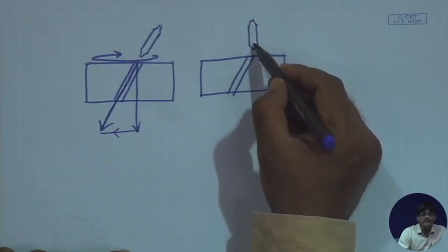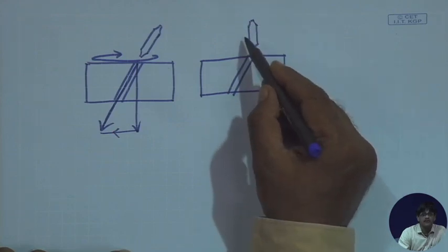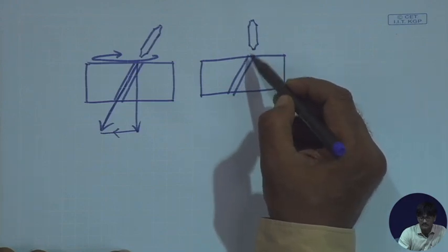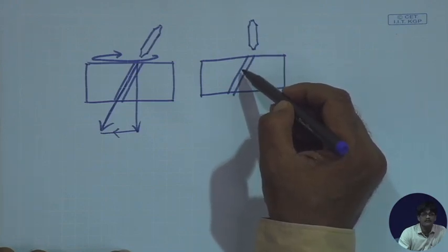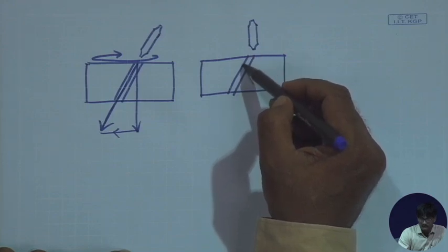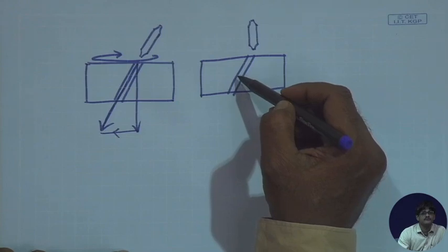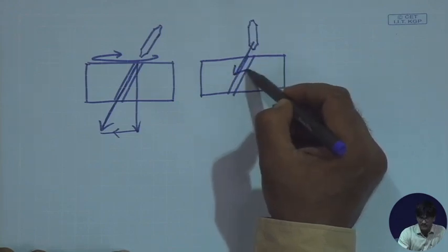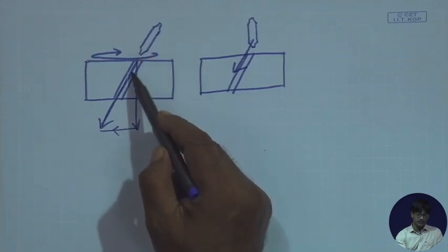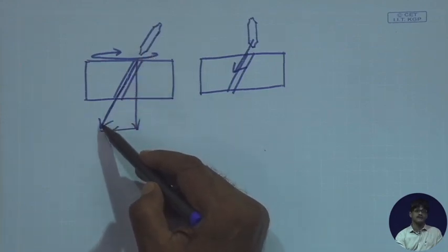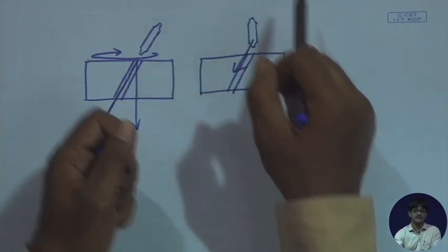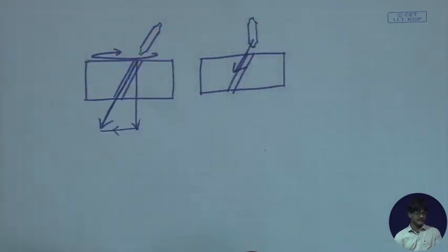In that case, had you not oriented it, this would have been the case. The cutter would have hit the job on its side. So, it is a sort of slapping action. It would not have cut at all. It would have cut and brushed, and the whole thing would have been spoiled. Just imagine it trying to move this way. So, orientation of the cutter so that it follows through the cut is very important, and that is what we are doing by rotating the table about a vertical axis.